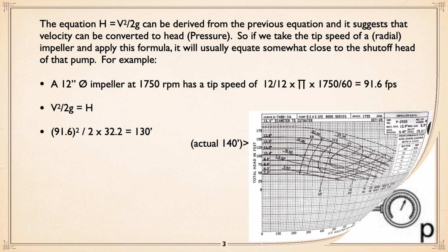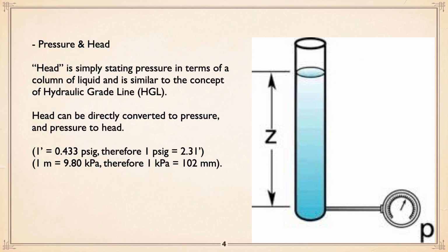Now, pressure and head are sort of interchangeable. Head is how high is the column from the point you're measuring, and depending on the specific gravity, which with water and sewage is 1, that can be converted to pressure. Now, quick comment, Canada is on System SI, which is metric system with a few other mild variations. So I've tried to show both that and American units, which I must admit I'm more familiar with. Like 1 foot of head equates to 0.433 psi. Therefore, 1 psi equates to 2.31 feet of head. The two are convertible.